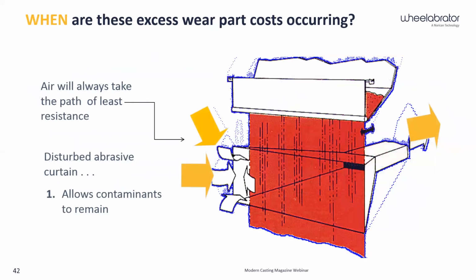Again, going off of the last couple slides ago, if that curtain is disrupted in any way, that air is taking the path of least resistance. It's lazy, so it's going to draw through on an edge like that, and you're not cleaning your abrasive effectively.